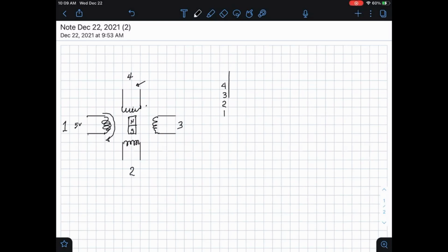And then, let's make this table here. So, in the first position, we can turn on, let's say, 1, 0, 0, 0. No, let's turn off all the rest of the coils. And then, what will happen is that the permanent magnet in the middle will orient to 4.